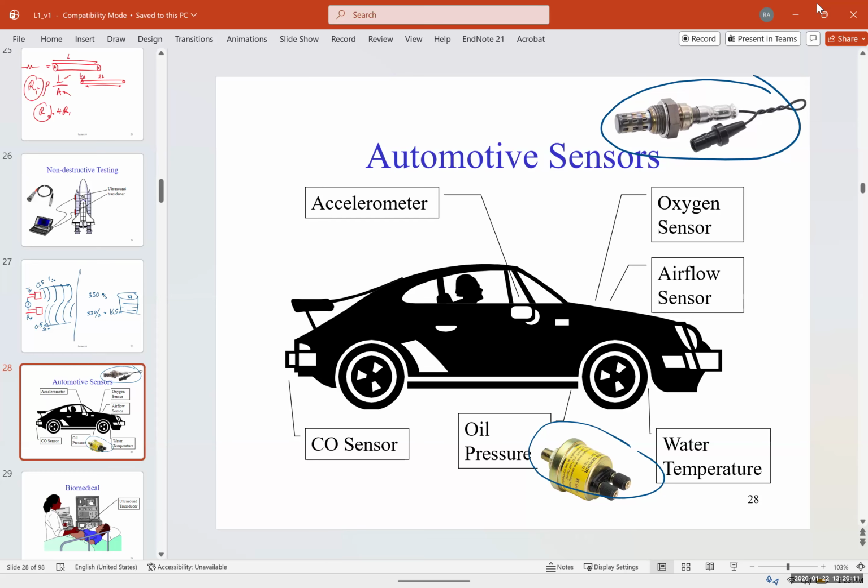One other type of sensor is a sensor that they put in the fuel tank that actually measures the amount of octane. If a car has a turbocharged or a supercharged engine, they usually perform better on high octane gas. But you have to adjust the fuel. Most of these new cars know what type of gas you put. So if you put an octane of 87, it's going to adjust the airflow sensor and the injectors to pump different values so it has peak performance and doesn't have knocking in the engine.